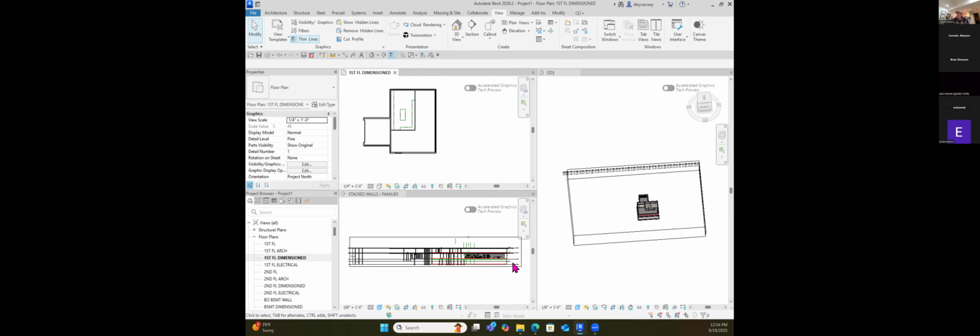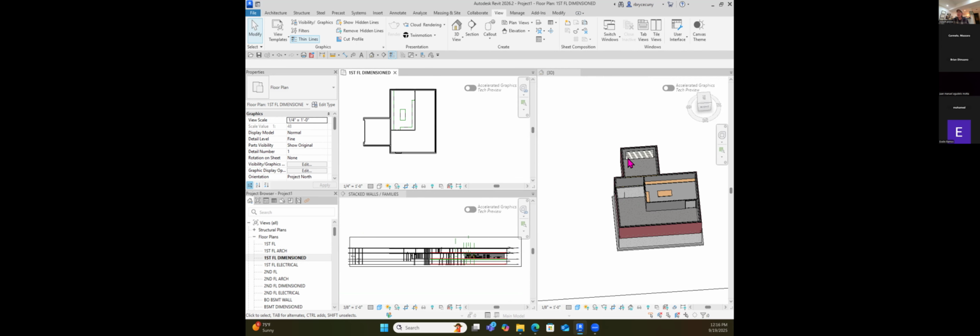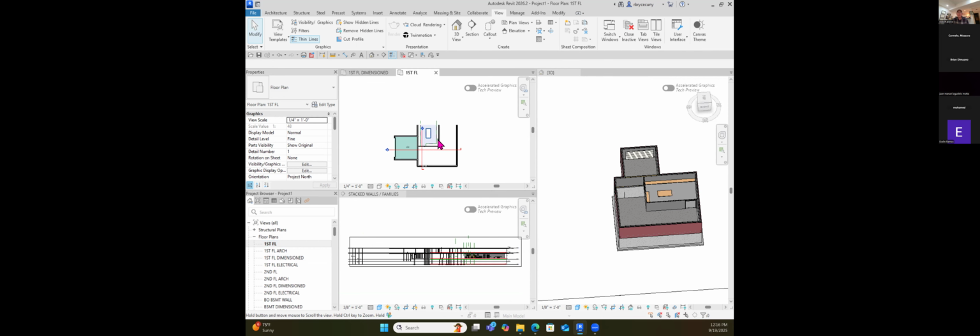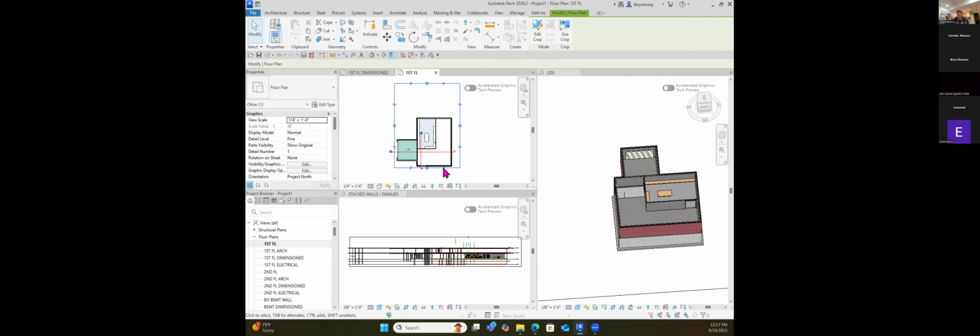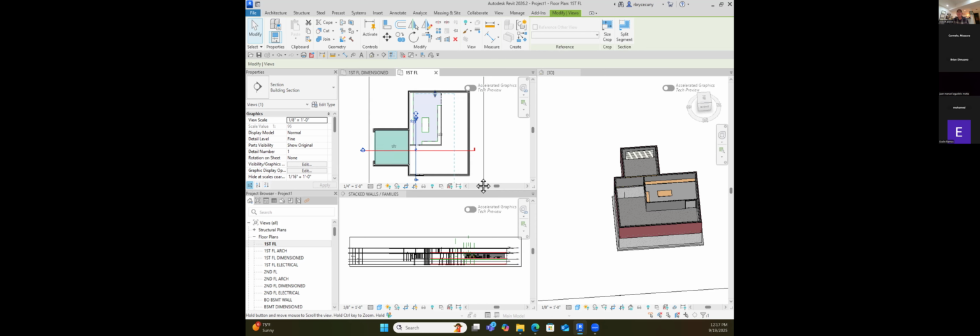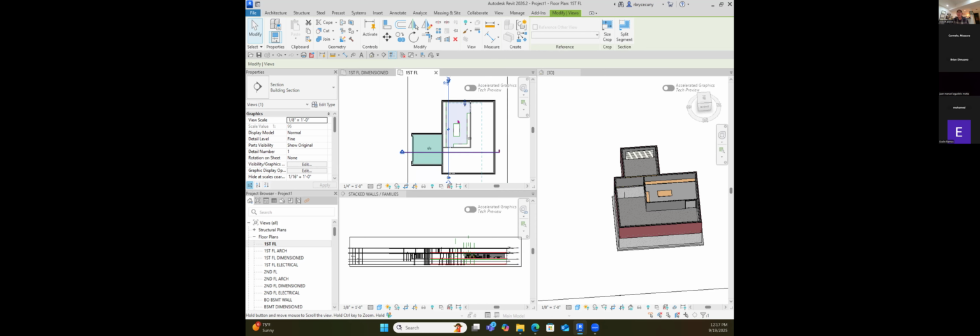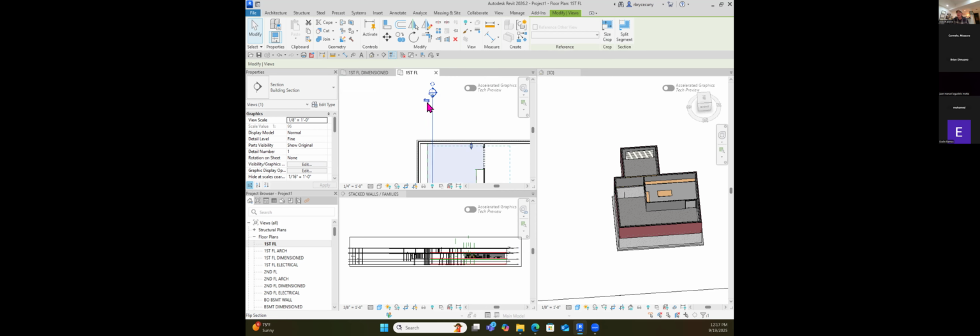I've got the library of all of the components that I want. And I have my 3D view. And let's make a fourth one, which would be the section through here, just to make it easier. Now I can't see the whole house because why? Because my crop region is telling it to only show the stuff inside of the crop region. I have this section, which I want to look in the other direction, see where the arrow is. That's the tail and the arrow. So I want it to look the other direction.